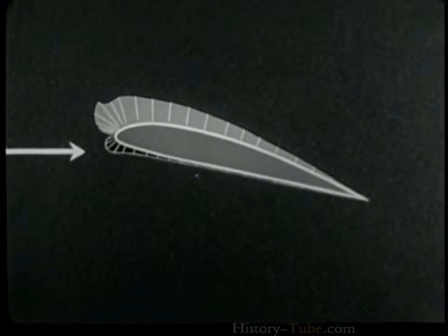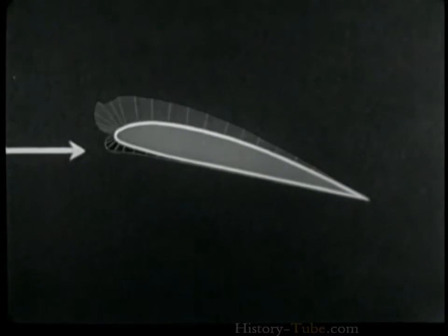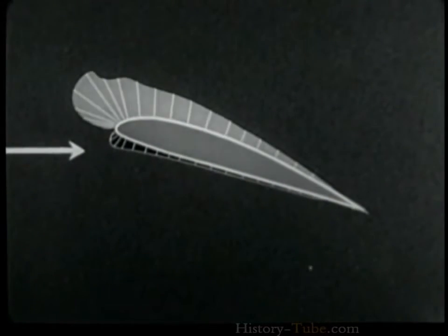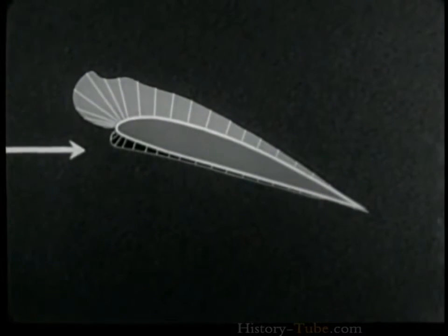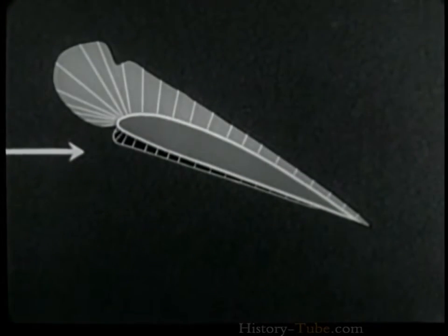The wing is now approaching its stalling angle. Positive pressures have changed very little in either distribution or value. The negative values, however, have increased somewhat, especially at the leading edge. By further increasing the angle of attack, positive pressures remain practically unchanged in both value and distribution, but the value of negative pressure continues to increase. At this angle of attack, the wing is well past its stalling angle, yet the positive pressures show little indication of change.